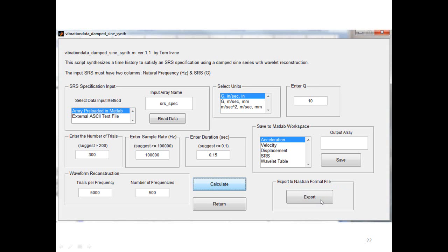And that's useful. You could call that NASTRAN file into FEMAP, for example, if you use that as your preprocessor. Or you could just bundle the file together in the case control deck for your NASTRAN run. Okay, but let's go ahead and show you.